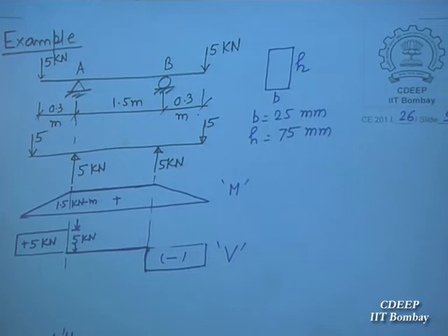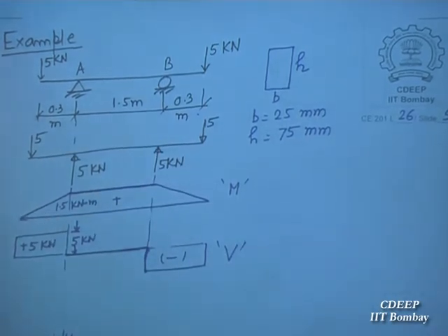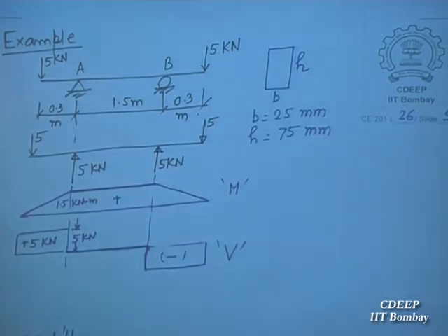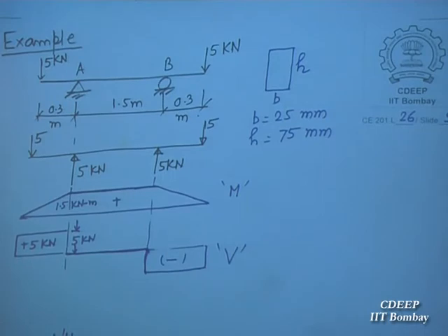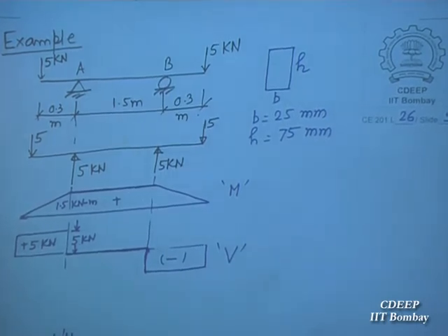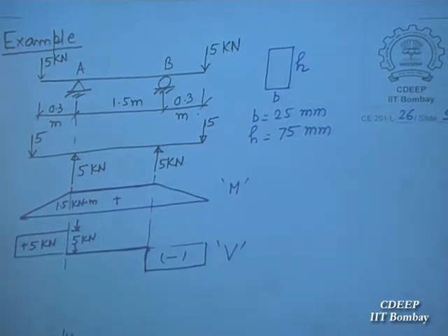You have to mix sand, cement, aggregate, mix water, then place it. You will tell them to put this much water, they will put a little more than that. So the whole stress, everything changes. So we give a factor of safety of 3 for concrete.